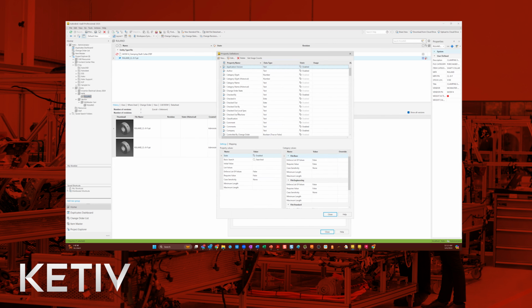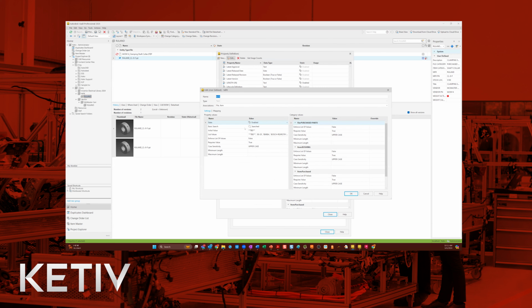You're going to see a variety of options that are set up here. So initially, when you create a new property, it asks you what type. Typically, you're going to go with text. It wants to know where is this particular property, or to what is it going to be associated. So in this case, at the file level, for manufacturer, I only want that associated with purchased parts, so no other file category. So it's only selected to show up in the purchased part category here.